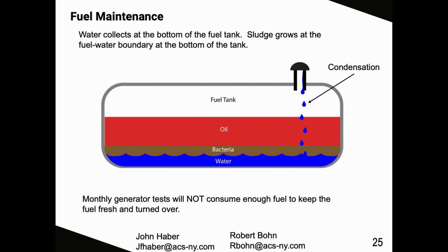Monthly generator tests will not consume enough fuel to keep the fuel oil fresh and turned over, and that's monthly. Again, most tanks are not overturned within a month, so it's very important to keep things ready to go for your emergency generator systems.